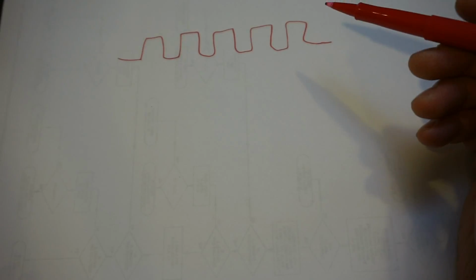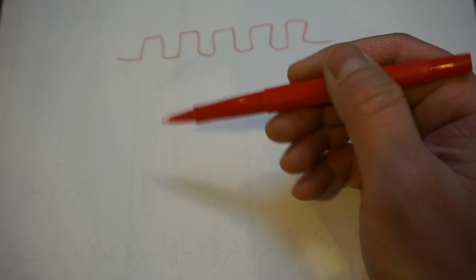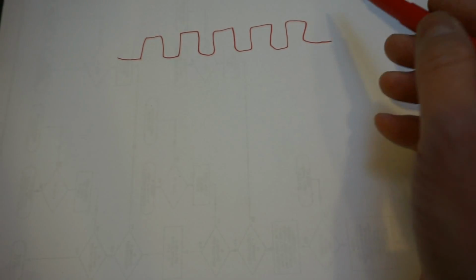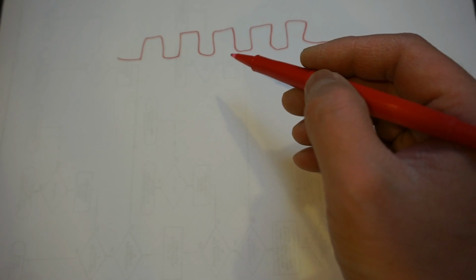And remember, in our previous standard counting method, we essentially set a time interval here, and we are counting how many of these unknown pulses are there within that interval. Here, we're using a slightly different method. Instead of setting the time, we're using the input pulses to set the time. So the gate opens and closes by the edges of our input signal.